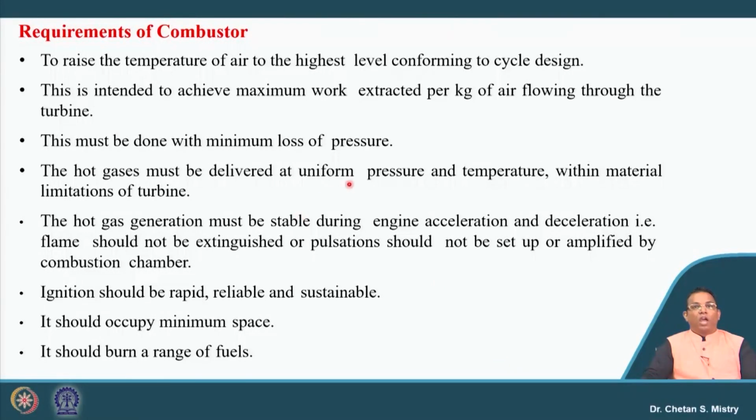It needs to have minimum loss in pressure. At the same time, hot gases should be delivered at uniform pressure and temperature, within the limitation of my turbine blade material. At the same time, we need to accelerate and decelerate the engine, so accordingly we need to vary the flow rate coming out from the combustor. It should have ignition that is rapid, reliable and sustainable. It should occupy less space and it should burn a range of fuels.